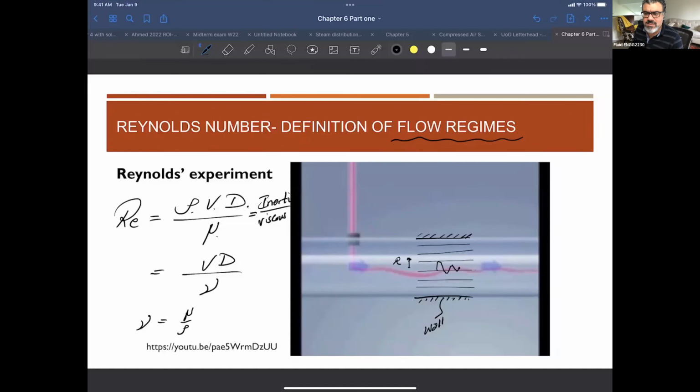The transient is a condition that we don't deal with too much as engineers, because this condition between turbulent and laminar is a very small area between the two. It's not something where, as an engineer, we should design a system working in a transient condition, so the transient case is not paid that much attention in engineering applications. But of course, in engineering sciences, when people are interested in a very critical location where the fluid has to be transient, there's no way around it, so you have to get into much more complex analysis for that.